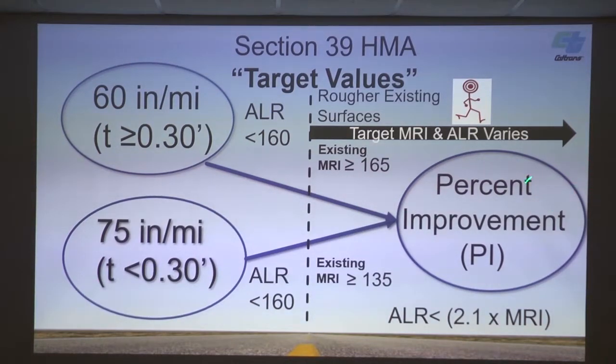So now our designers have to kind of design for smoothness. They need to build in 2 opportunities, either milling in one shift and paving in a different shift, or a thick enough lift where they can break it up into 2 lifts. Designers have to account for that now. In the past, they basically just put a lift out and said 1500s, you've got to get a 75, and that led to a lot of claims. So we're going to make all those claims go away. We'll still get claims, but they won't be as legitimate. Not that they were legitimate, but